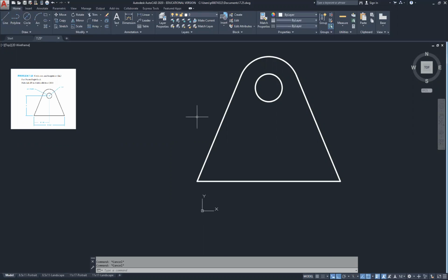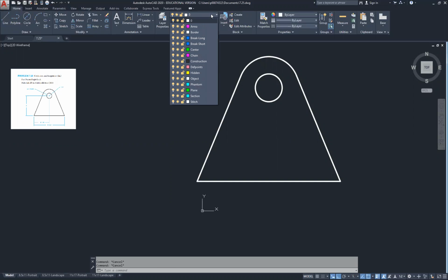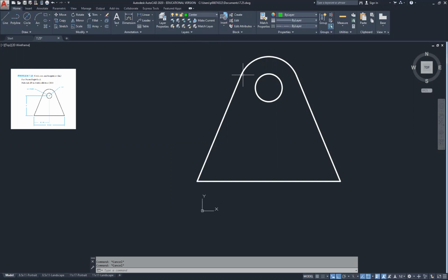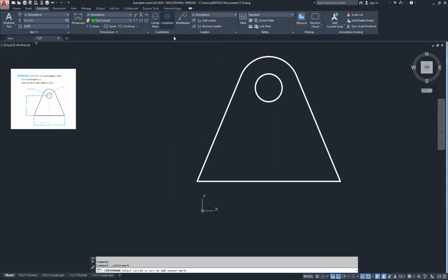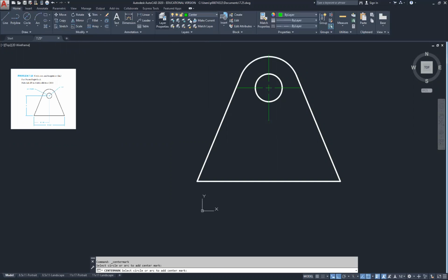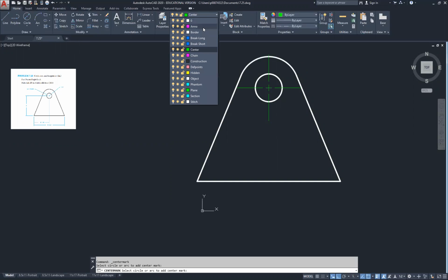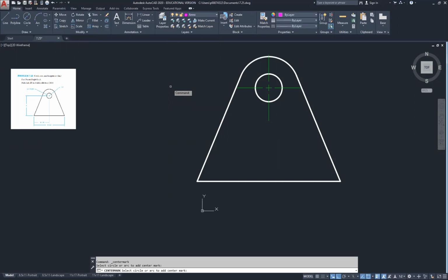All right, now we can start annotating. We're in the annotations. Let's make sure we're doing our line types. Let's start with the center line, get that out of the way. Go ahead and annotate, center mark, and click on the largest circle. That puts our center line in place. Back to the Home tab, change this to the Anno layer. And now we can start our dimensions.